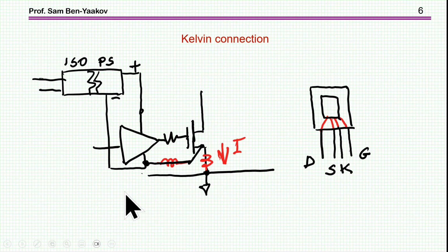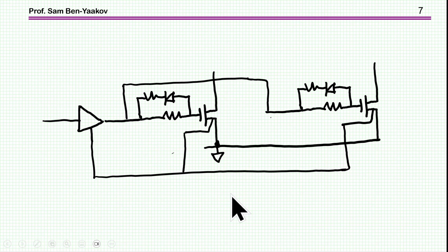It requires, of course, an isolated power supply for the driver, which you would like to have anyhow in the case of high current, and of course all this is related to high current, high power circuits. So you need an isolated power supply which is supplying this driver. However, there are some problems here that I'm going to address.